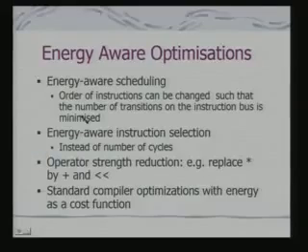The other thing could be energy aware instruction selection. Instead of looking just at the number of cycles, it would look at the combination which would minimize the energy consumption. In fact, this also becomes part of design space exploration. What are you exploring? Different possible orderings of the instructions. And in a way, this exploration can be done with reference to each hardware unit that you are using in an embedded system.